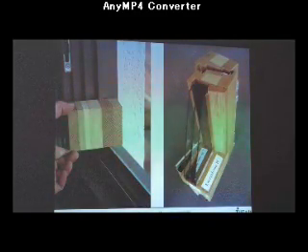The original windows in these existing buildings are steel frame, single glazing windows. In this renovation, wooden frame and triple glazing windows were adopted to replace the original windows. This is the section of the wooden frame. You can see there are several insulation layers in this frame, and these insulation layers can improve the overall performance of the window.